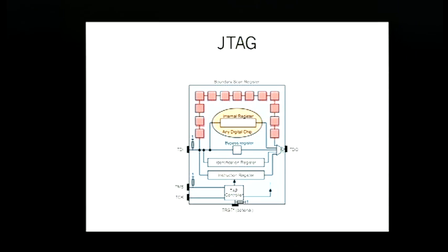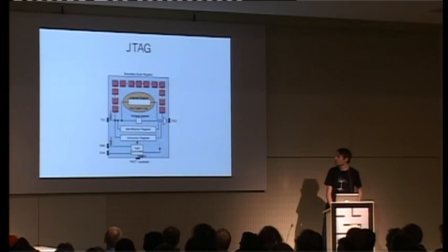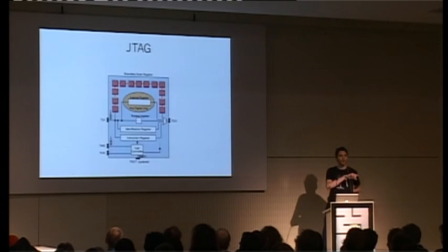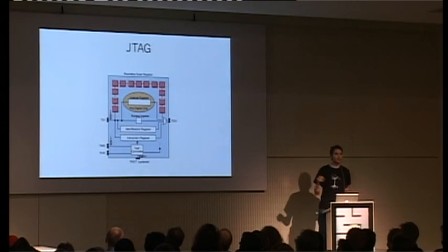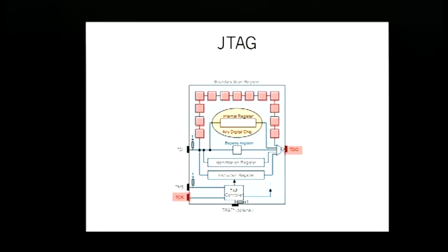So we would only need TCK and TDO. But when you deal with multiple registers, that's where the different pins become important. So with this particular register, which is a boundary scan register, you can check the state of all of the pins on the chip, as well as some internal registers. Here, again, just to read the boundary scan register, you need the clock and the output.